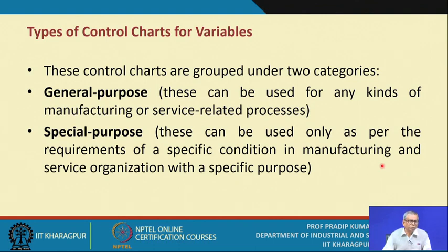Now the second purpose is very important. The second purpose is if there is any shift in the process parameter value. Is it okay? Now obviously if there is a shift, you conclude that the process has gone out of control. Whether your control chart is able to detect this shift or not as quickly as possible.